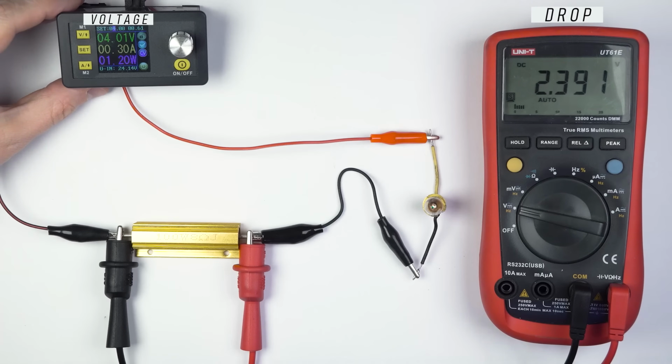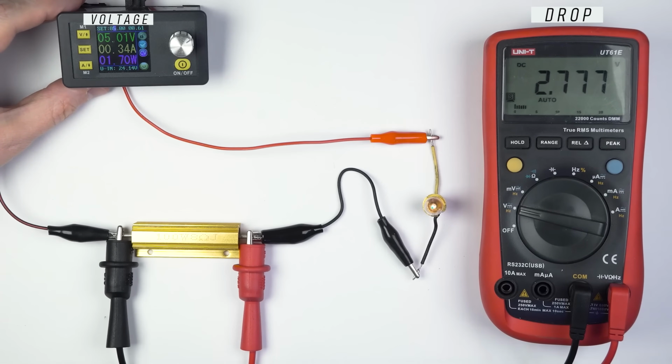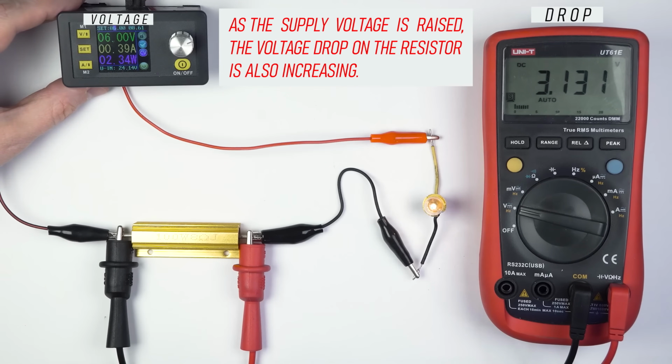One very important aspect must be understood. The amount of voltage drop across a resistor depends not only on its value, but also on a whole number of factors: current strength in the circuit, load behavior, power supply voltage, etc. So the drop on a fixed resistor is not constant and may actually vary. This means we cannot use this component to build a voltage stabilizer. But we will talk about step-down converters a bit later.